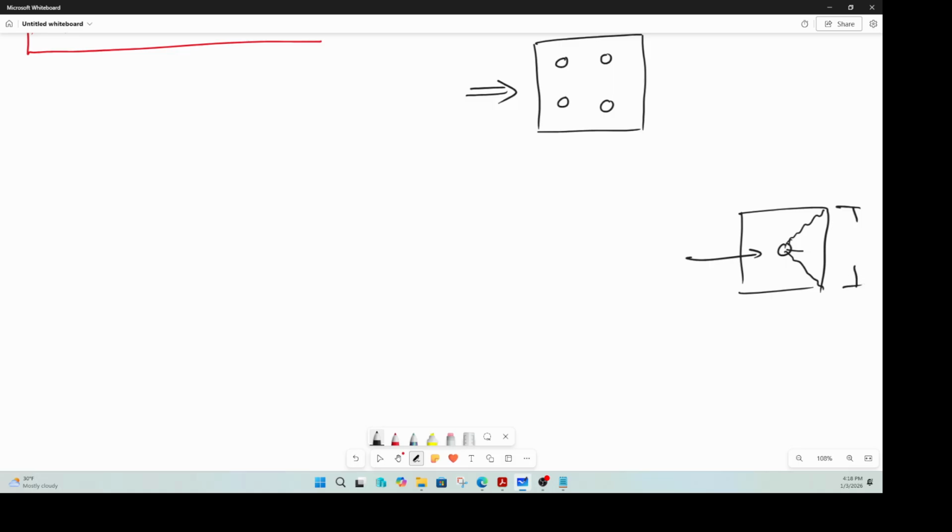The width of the failure surface is 1.5, and let us say this distance is the CA1 edge distance. In this case, we'll have to find out what our CA1 is, but let's say that is CA1. Then 1.5 CA1 on this side from here to here, and 1.5 CA1 from here to here. So this is 3 CA1. That is the length of our failure surface. Okay. So in the problem description, let's calculate the CA1, CA2 and see where we stand.